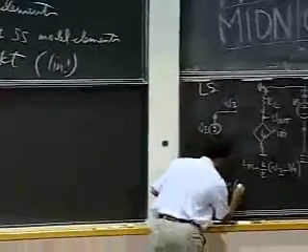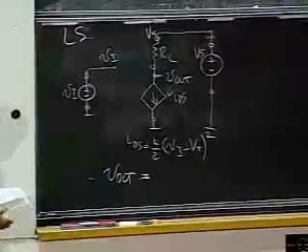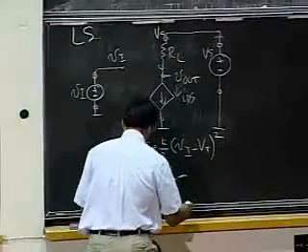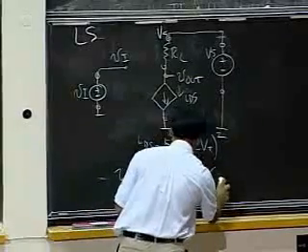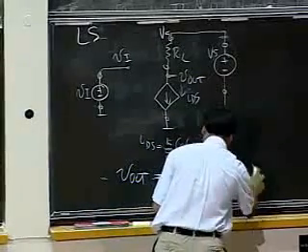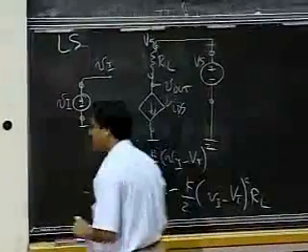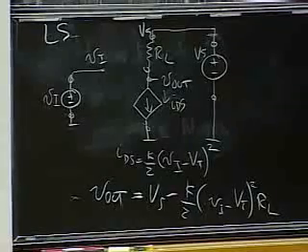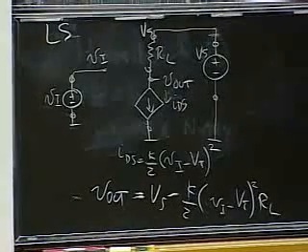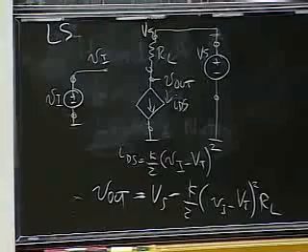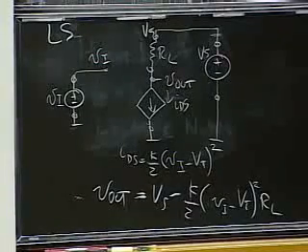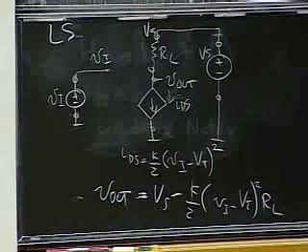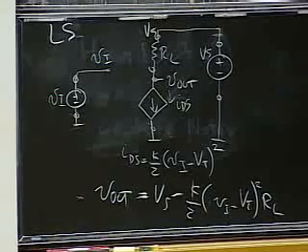I get my V out being equal to, we've already done that before. Let me just write that down out here. Don't worry about copying that down. It's on the last page of your notes. So the first step of the method simply applies the large signal model and finds out the behavior of that circuit to find out what the bias point values are.